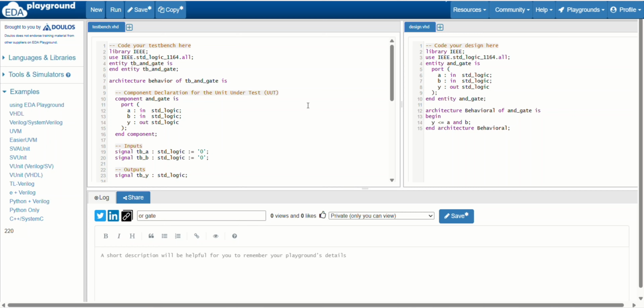In this video I will take the AND gate only and make some changes to it, not many, because everything stays the same except the internal structure, meaning the architecture part. The entity name will also be different. You can keep it the same, but I suggest changing it, as it is better for getting the output and saving the code. I will show all the changes needed in the AND gate so that you can get the OR gate, NAND gate, NOR gate, XOR, and the NOT gate also.